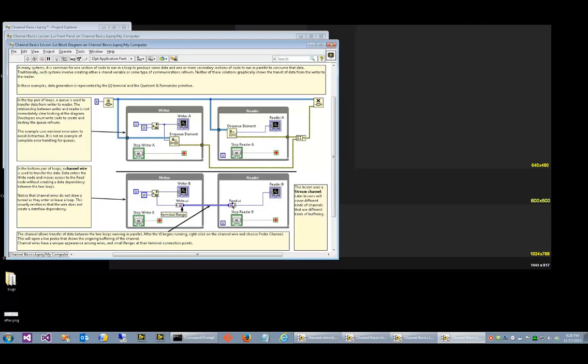That's what makes the in-placeness algorithm that some of you are familiar with, when it sometimes goes wrong. It doesn't happen very often, but occasionally some of you have had reason to talk to us about it. With this memory optimization, we're playing the same game here: we're able to look at this and say we know we need a reference for the lifetime of this wire, and so we'll keep it around for the lifetime of that wire. It's not quite as simple as that, in the same way that LabVIEW leaves memory allocated in case you re-enter the VI, so things are already inflated. But it's a reasonable enough approximation for you to understand what's going on here. We know from the compiler side if it's going to last for this long.